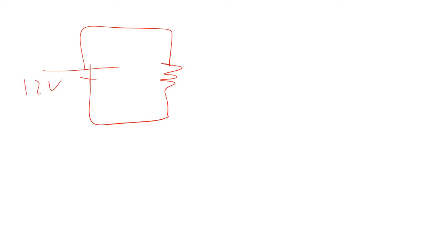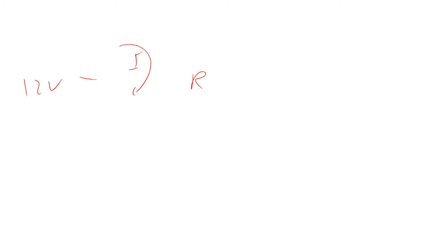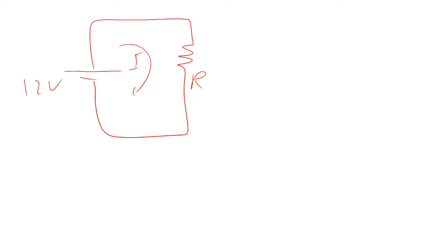We work this the same way. We imagine this as a resistor on a battery. So 12-volt battery, resistance, we find the current. Okay, and so what we do is we have to find the resistance. So the resistance is rho L over A.